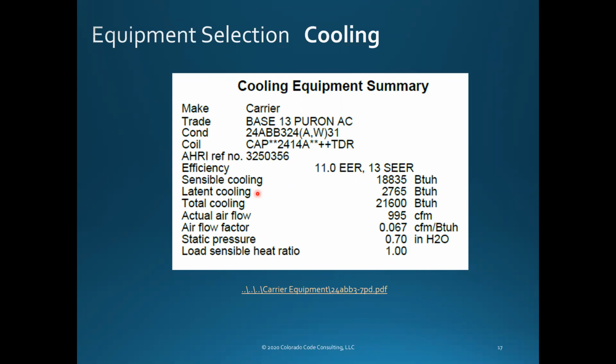Okay? And so as you can imagine, how much moisture-laden air is actually hitting a cold coil in your environment there in Colorado. It's very dry, right? We don't have a calculated latent load there. If you've got an air conditioner in your house and you go downstairs or you go down, where the AC is at, do you see water trickling out of your condensate pipe? Probably. So there's clearly some, right?